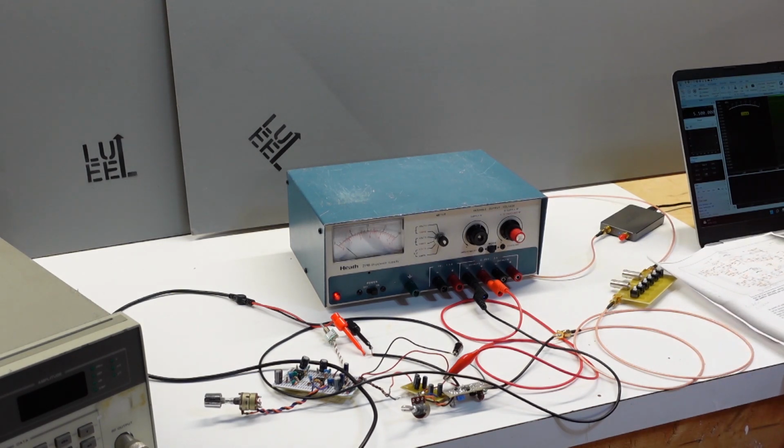Now, I was a bit naive. I was thinking, I'll just set this up and drive it into my spectrum analyzer and I'll be able to look at the third order intercept. Well, I overlooked a small but mighty detail with my spectrum analyzer. You really need a super fine resolution bandwidth on the order of 100 hertz. And my home-built spectrum analyzer, its tightest filter is only 30 kilohertz. So, that is not going to work.